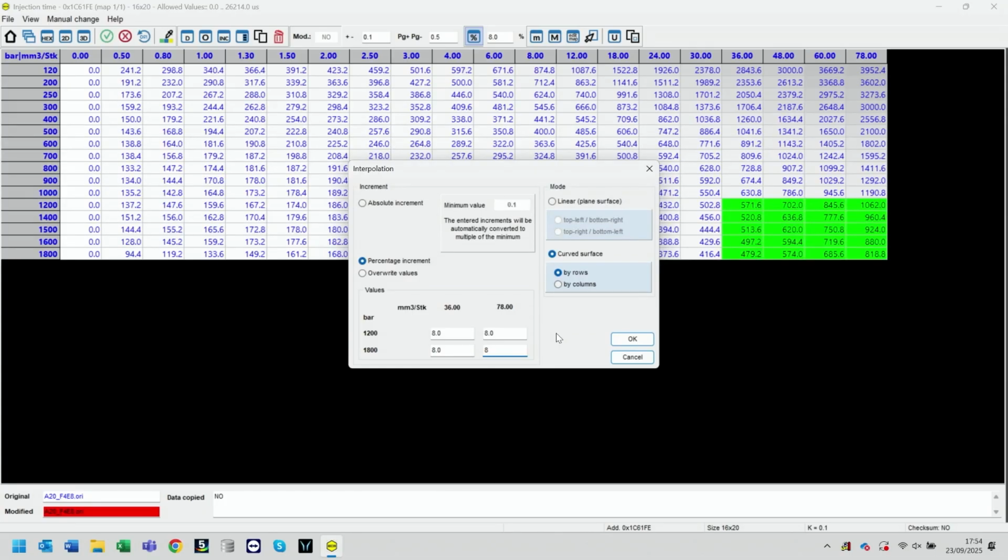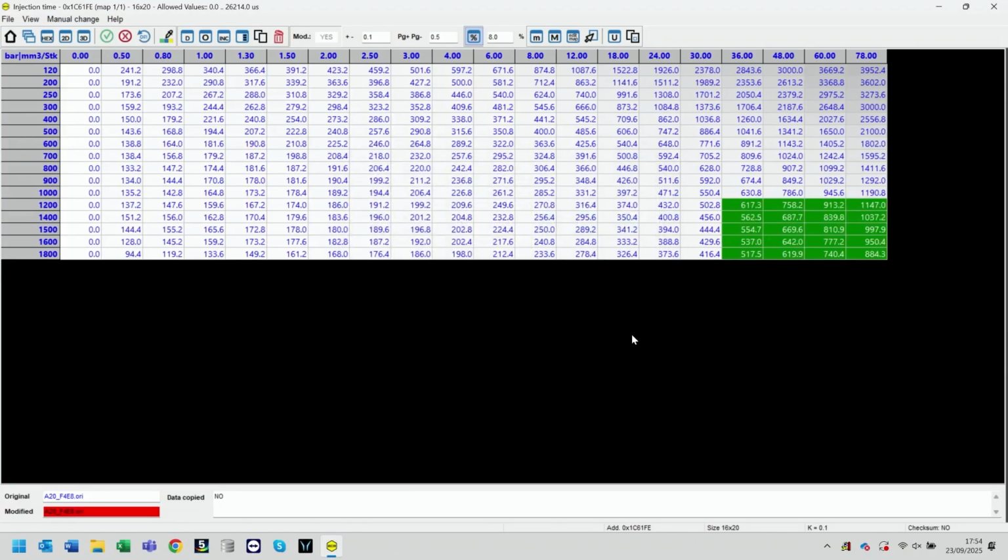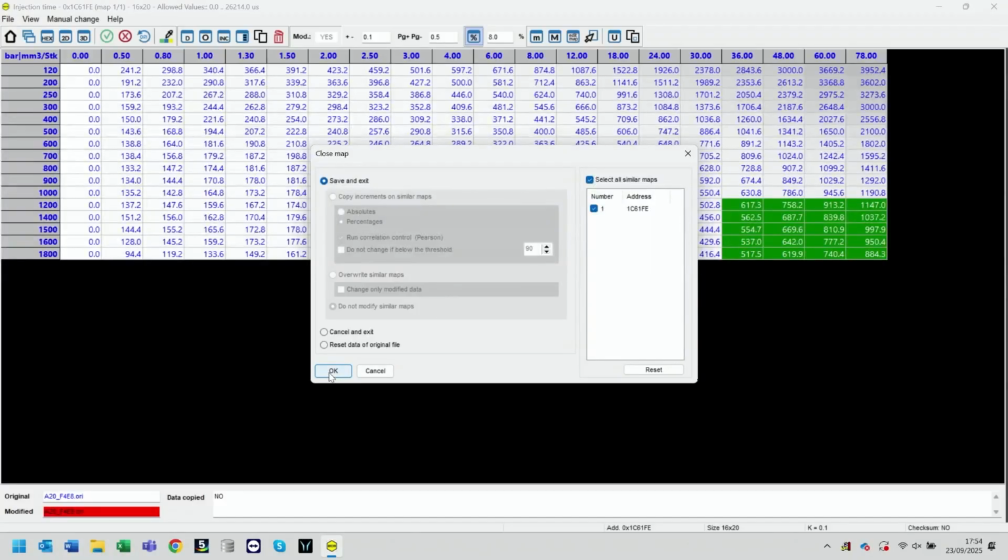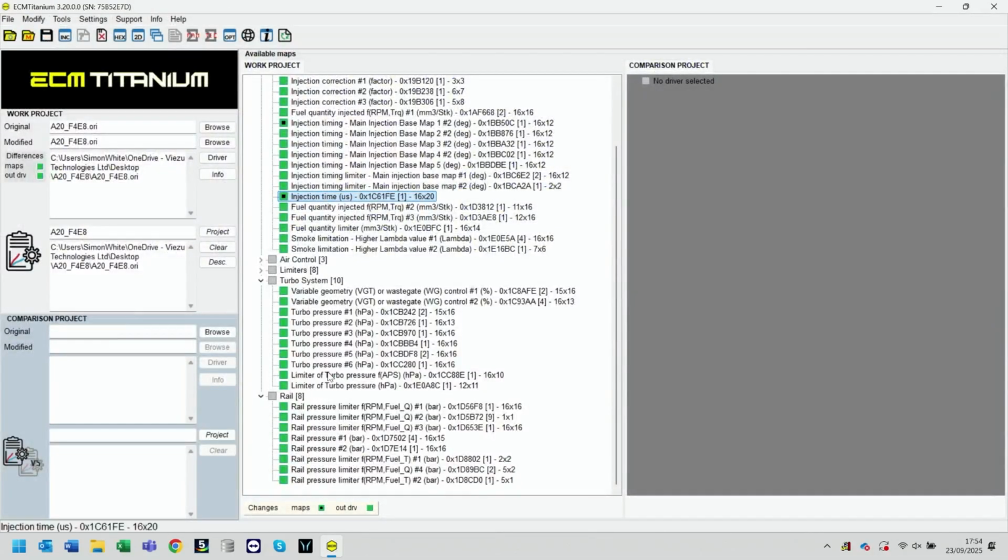It's all about consistency across the engine. It's almost like you know what you're doing. There is logic to the madness. You may find on a particular vehicle you need to go a bit stronger on the fueling. You may find on a particular vehicle you may need to go a little bit less than that on the fueling. But this is where your validation comes in when you're dyno testing or road testing in controlled conditions with your data logging, making sure the vehicle is responding how you expect it to respond. Very good. So let's minimise the fuel.